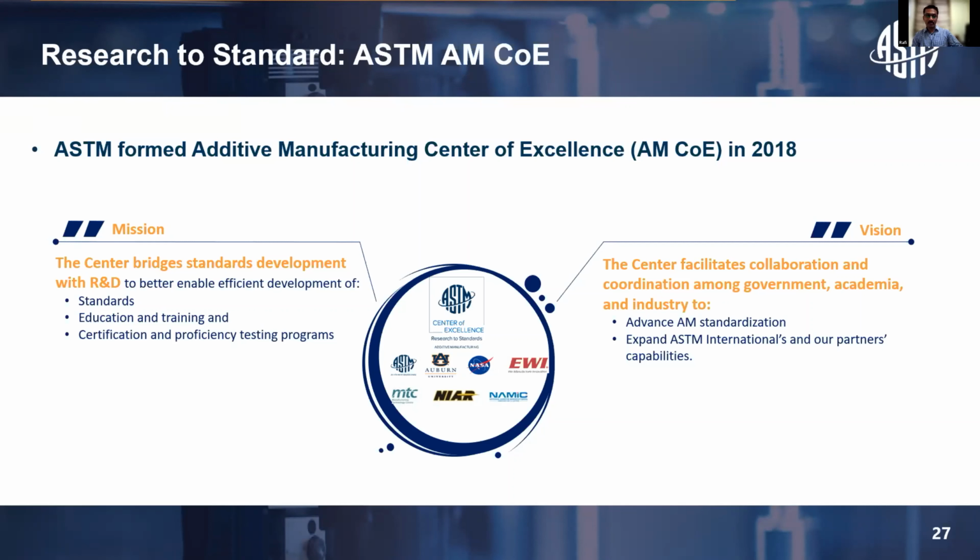For example, for powder development there is an AMS spec, which I think is the only spec I know of for qualifying a material or powder manufacturer. They can use that standard, AMS 7002 series, say they are in compliance, and use a third-party certification body to verify that they comply and get certified.